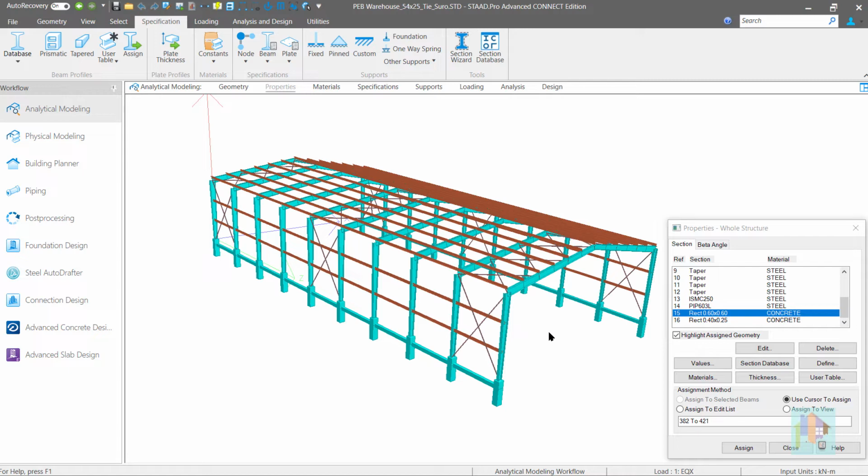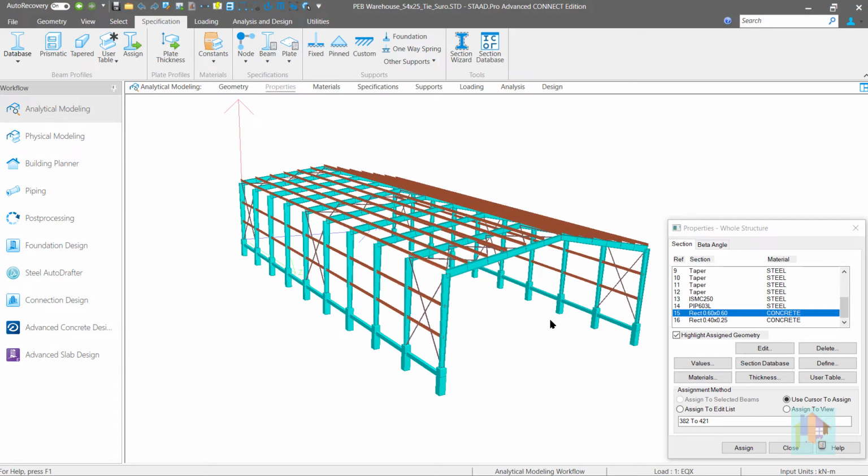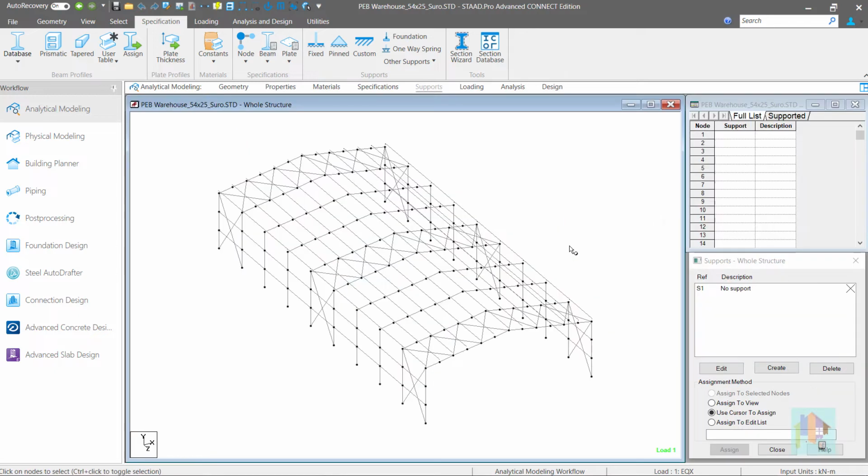To design the tie beam using RCDC, we can model it along with the pedestal, and for such a case, it is better to consider the fixity level as foundation top. I think it is clear now how to finalize the support condition and fixity level.